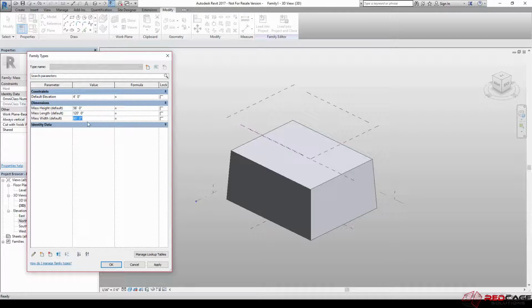Okay, so you'll notice that I didn't enter any feet symbols there. I just typed in the number. If I did need inches, maybe I would go back in here and type in 56 foot 6, and then I don't need to worry about the inches sign because I've put the foot in. But if I needed 6.5, then I would put a space and a half inches.